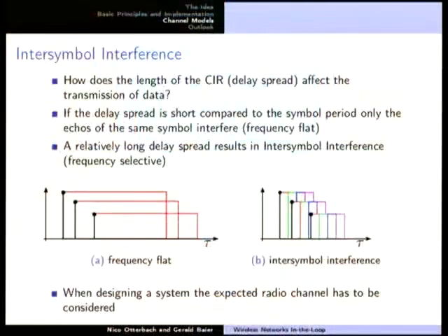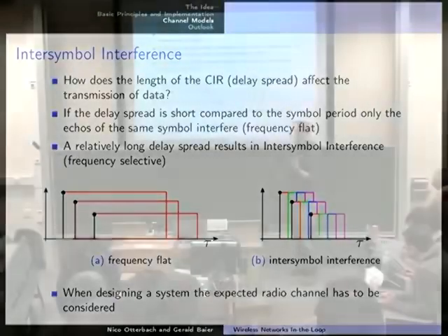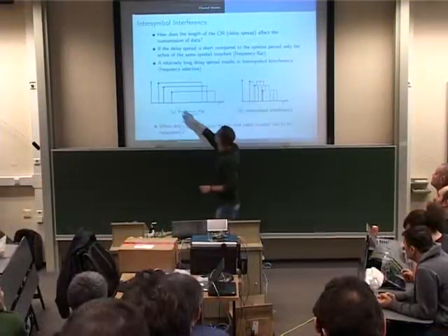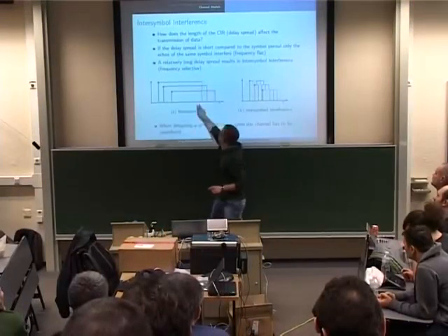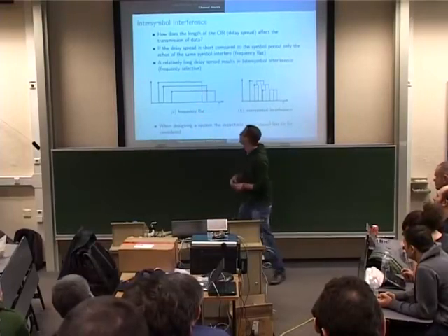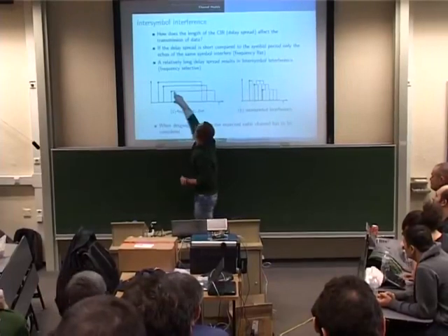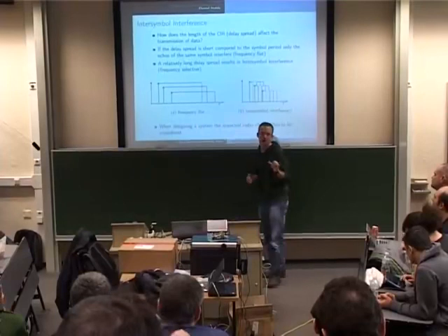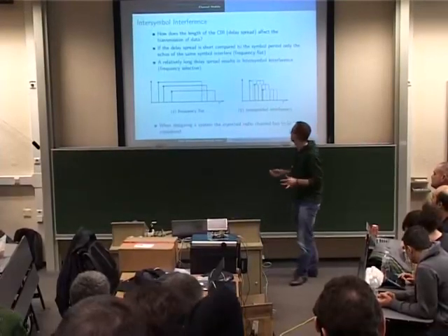So, just as an example of why the channel impulse response is so important, in both cases we have the same channel impulse response, with these short pulses over here. Now imagine we are transmitting with a very low data rate. So this example would be our transmitted signal or symbol, let's say just 1 bit. And of course we receive it on all paths, but we can see they all add up, because the pulses are very short and the symbol is very long in time.